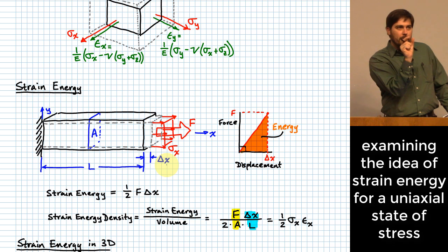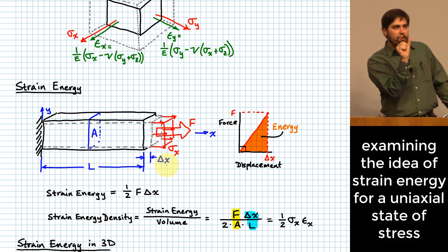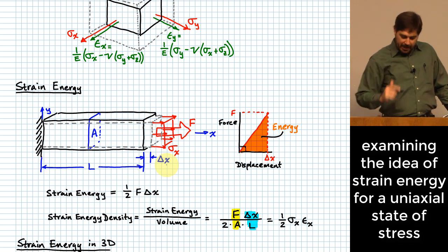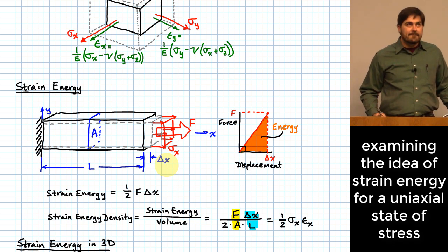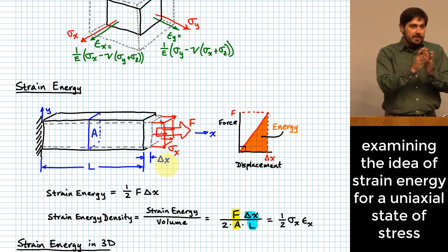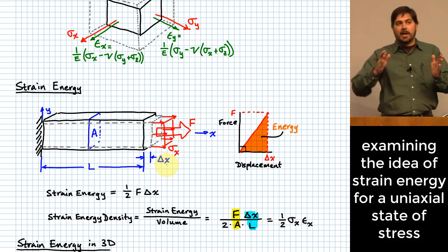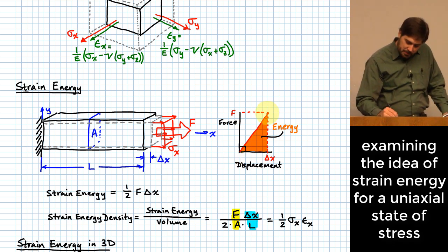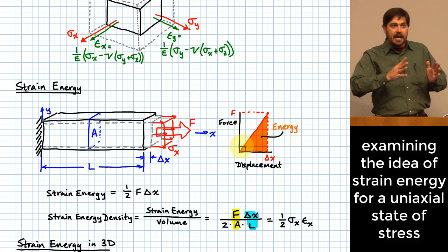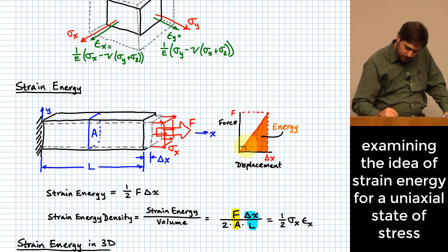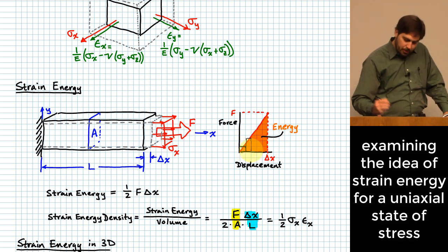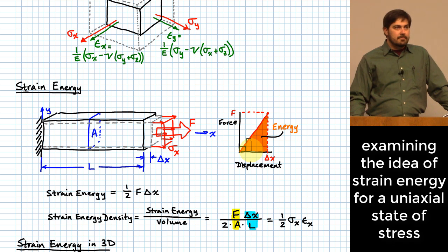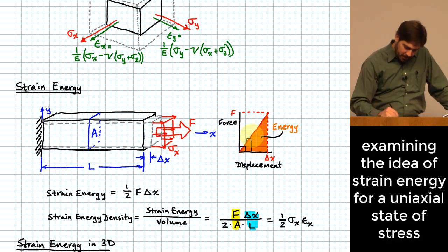Well, let's say you keep on pulling on it. You pull on it a little bit further. Okay? What happens then? Well, now this thing behaves like a spring, right? You keep on pulling on it harder, it's going to pull back with more force, right? And so you see there, the way that a spring works is that the amount of force increases as you begin to deform the material. Okay? So the next little bit that you have to deform it, you're going to have to put that much energy in. And then the next little bit that you have to deform it, you're going to have to put that much energy in.